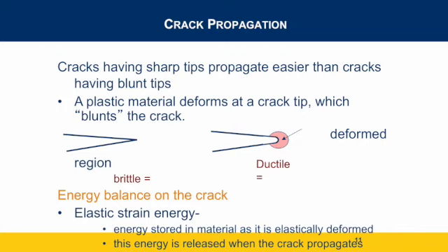All right, so this is the idea of crack propagation. It's more of a realistic look at it, right? So this would be a crack like I was talking about that you see in glass. Very small radius of curvature at the edge, very large A. This is a very brittle material. Ceramics act like this, and glasses, which are a subset of ceramics, versus ductile materials.